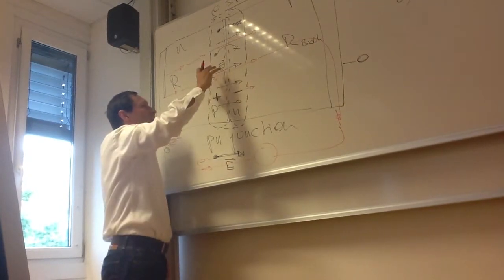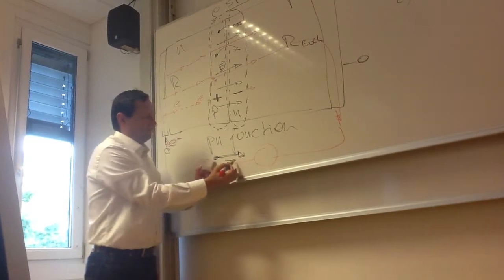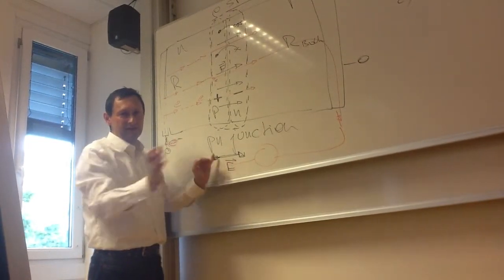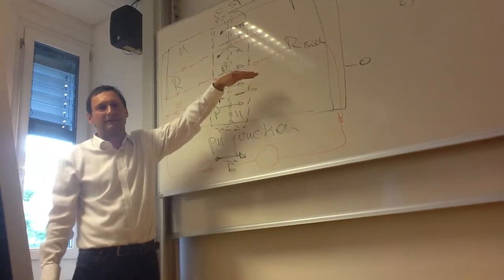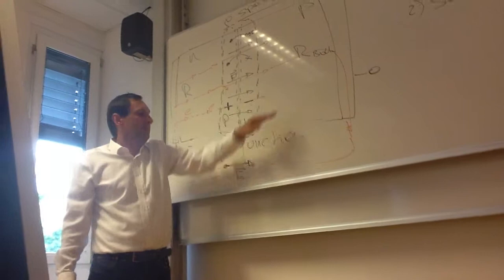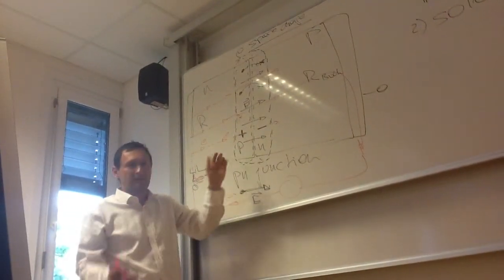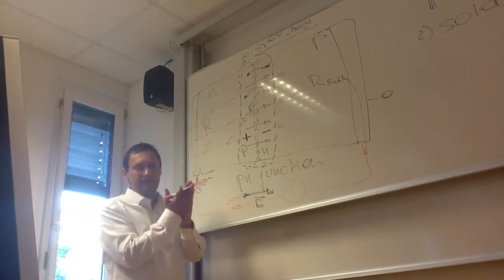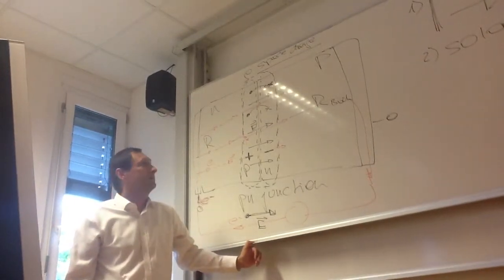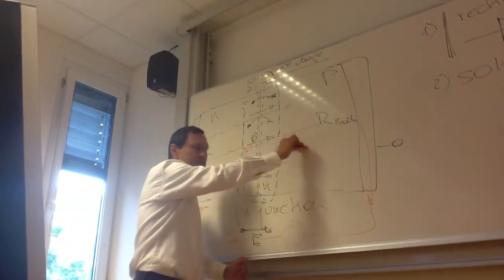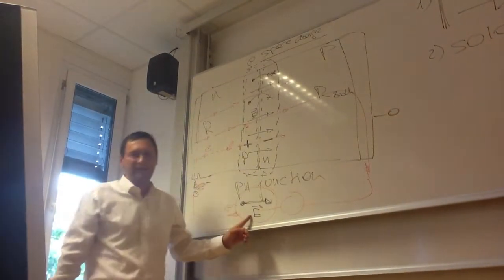So the electrons, if they are delivered from that side, saturate all the holes on this side here, and when all the holes are saturated, then also this electric field vanishes. There is no electric field, and the other electrons can pass nearly without resistance. But the effect of our electric field that's generated by combining an N and a P material is that we have some losses across our junction. So across this PN junction, we all the time have losses into the electric field.